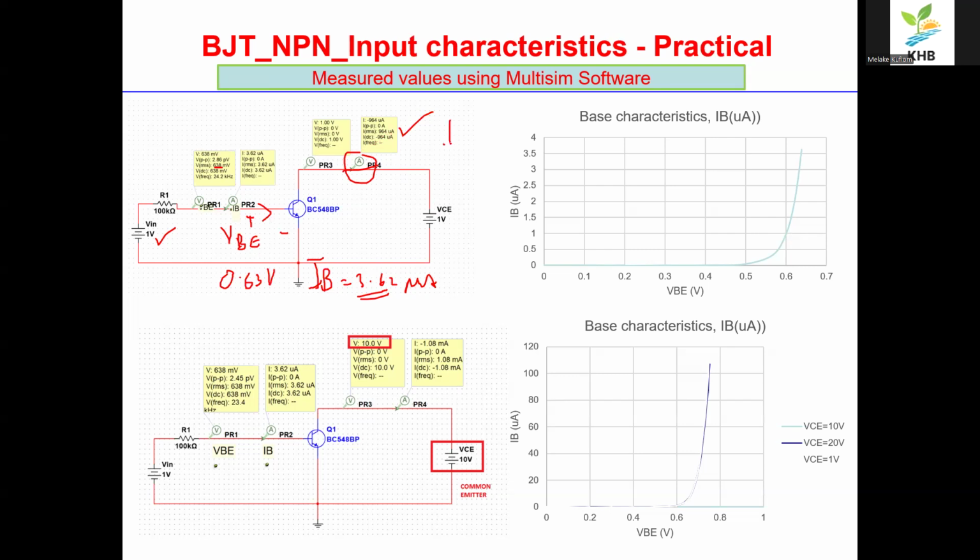That's why we draw a collector current by beta times IB. With a small amount of bias current, we can have a large collector current. Of course, this is just the forward region. I plot the results, and just around 0.6, the bias current increases a lot. And here again, whether we increase the voltage, it doesn't change the characteristics.